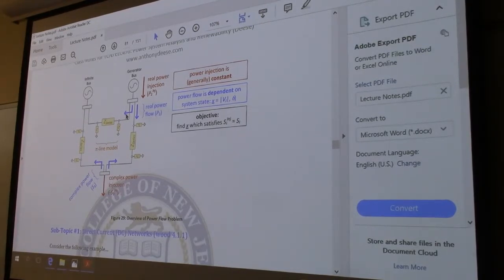Okay, so now we can solve for more complex systems, but it's really just going to be repetition of these bus types. More PV buses, more PQ buses added on. We get to larger and larger systems. Normally, we won't have more than one infinite bus in a system.